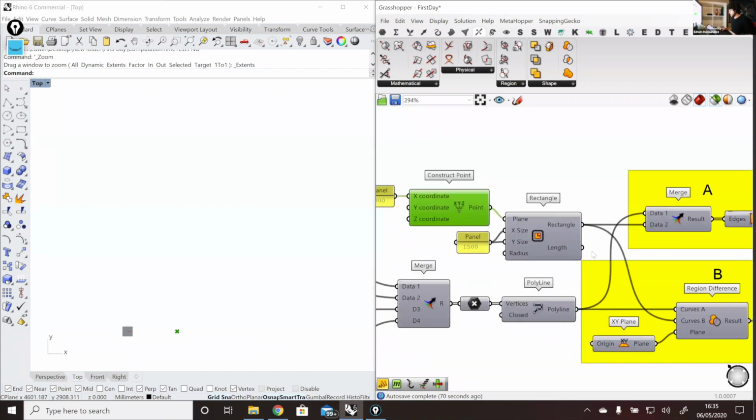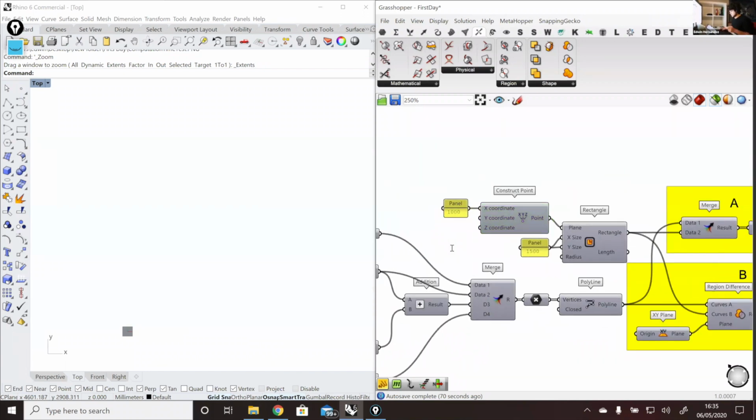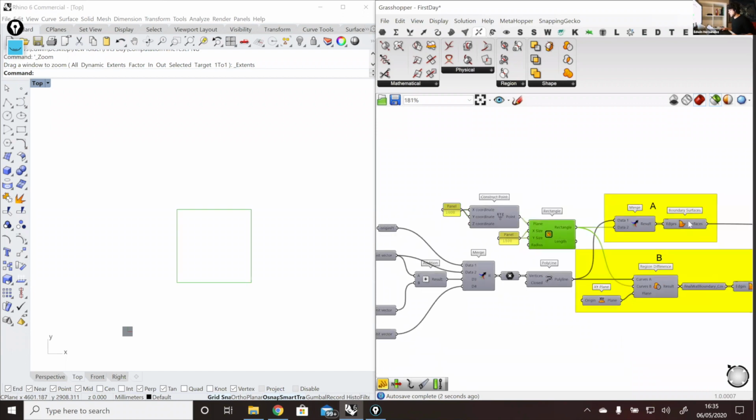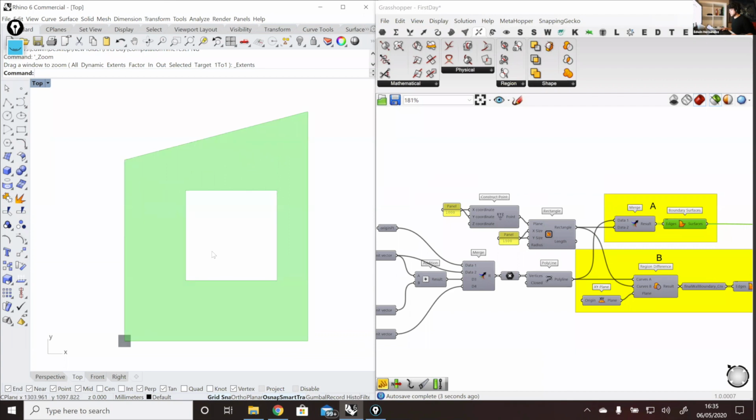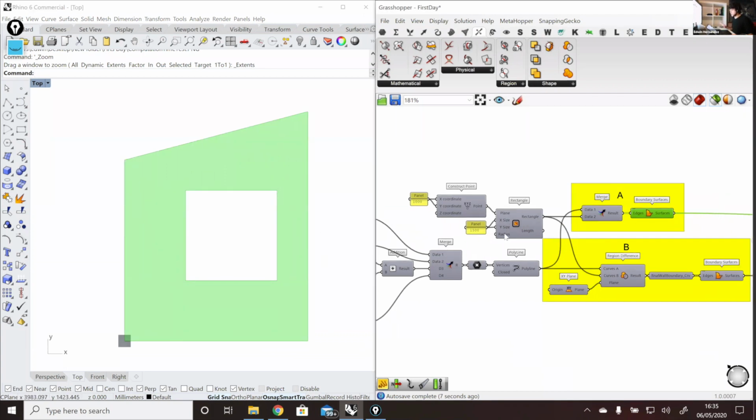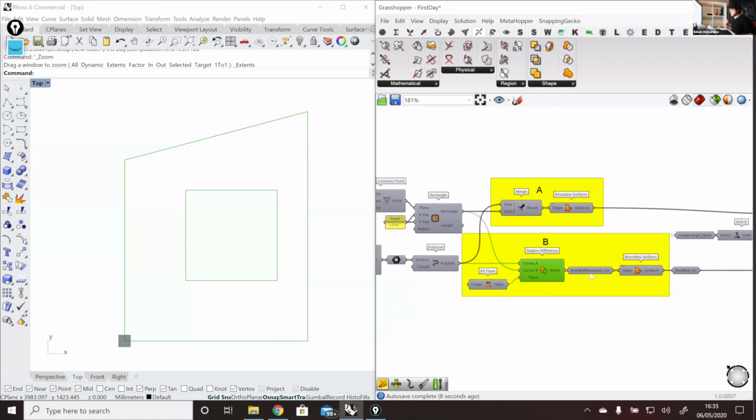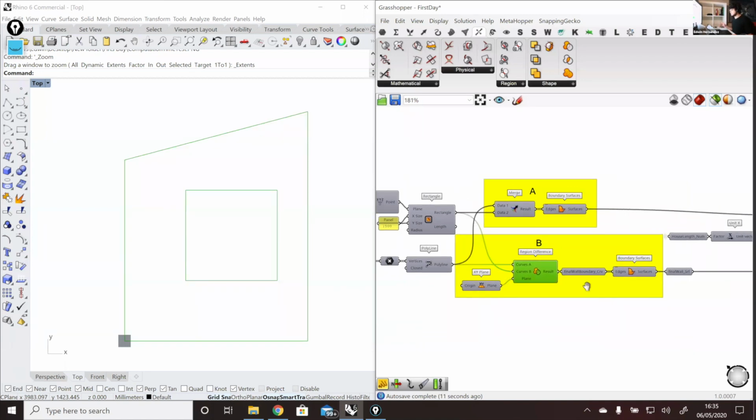But for example, here, if we know that this is going to be, I don't know, a window, then we can make this window. Okay, let's use this 1000 here. We can use this window 1000, so 1 meter above the ground, and then our region, our boundary surface works perfectly. Again, that depends on the use case, and how many curves you are using, etc.